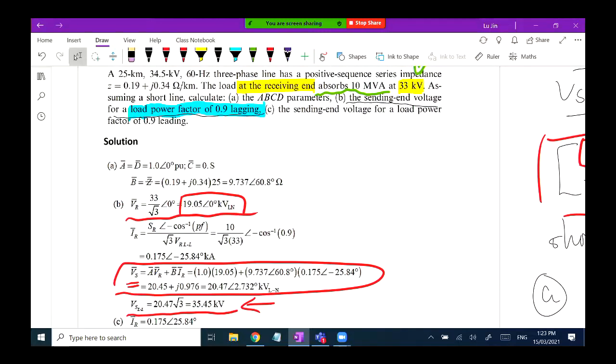It's just zero. S is the Siemens. It's Siemens, yes. Normally, you don't need to really worry about the units for these different parameters used in the ABCD model matrix, but they have different notations. If you move to the medium-sized transmission cable, you can see why we have this unit.